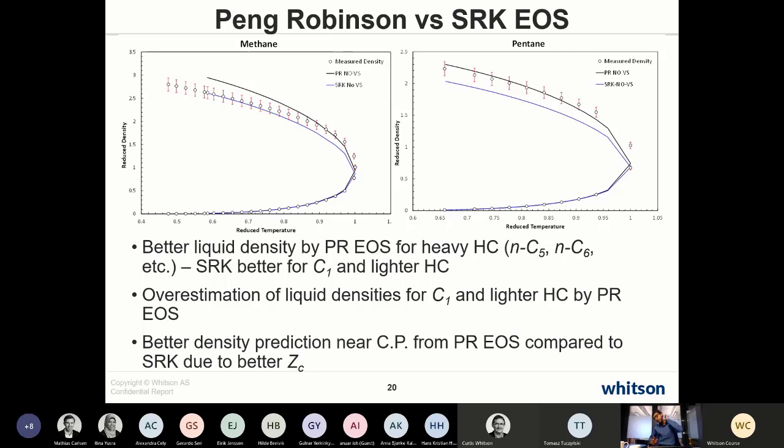One big challenge in the cubic equation of state model was to predict accurate liquid phase densities. It comes from this fundamental problem that we ignored the critical volume term in defining the values of A and B, as proposed by Van der Waals. So the liquid phase densities with the Peng-Robinson and SRK equation of state models were not satisfactory.